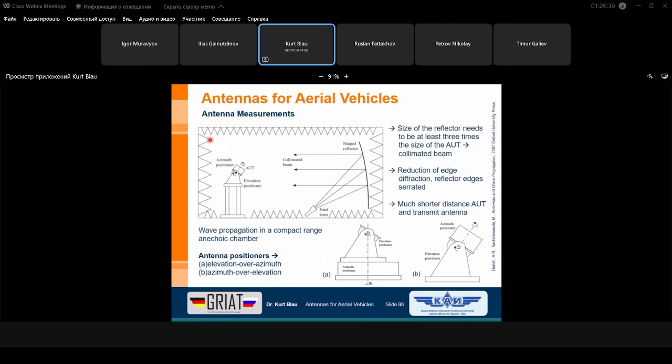It's filled with these carbon particles and ferrite particles, and then it's realized with external gas, and then you can make a foam from this material, and from these final foam blocks, you can cut out these absorber pyramids. It depends on the wavelengths, or the measurement frequencies, that you have to apply.